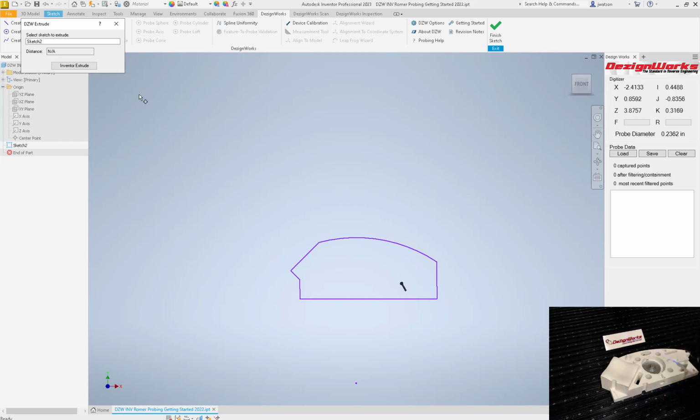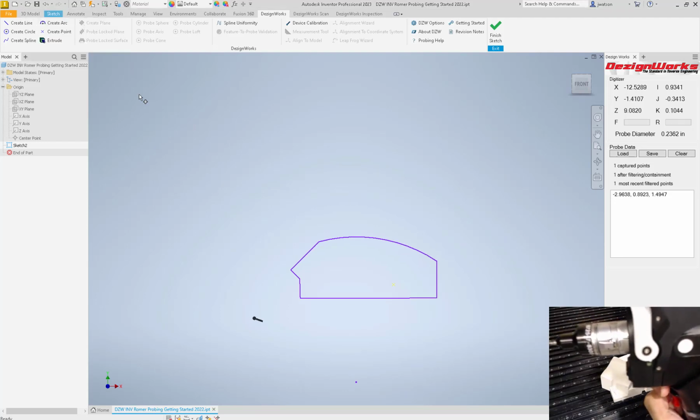What you don't want to do is called hooking the probe, where it's pointing back at the screen, like you're pointing like this. So you're holding the probe like this, anywhere from 90 to 10 degrees. You don't want it parallel. You don't want it like that. So 10 degrees and 90, tap the trigger, then press that button underneath to the right and hold it.